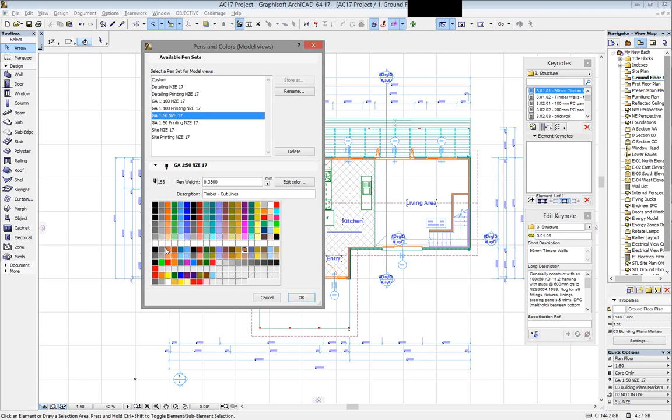What we're working on at the moment with the CADimage developers is a pen mapping tool, which will allow you to map the old pen 141 to the new location 181, and 142 to 182, and 143 to 183. This pen mapping tool will be very helpful for other things as well, like those of you that use these first 8 pens here, because you'll be able to map pen number 1 to pen 181, and pen number 2 to pen 182. So for those of you that are doing things in a non-international standard ArchiCAD way, this pen mapping tool might be able to help you out.